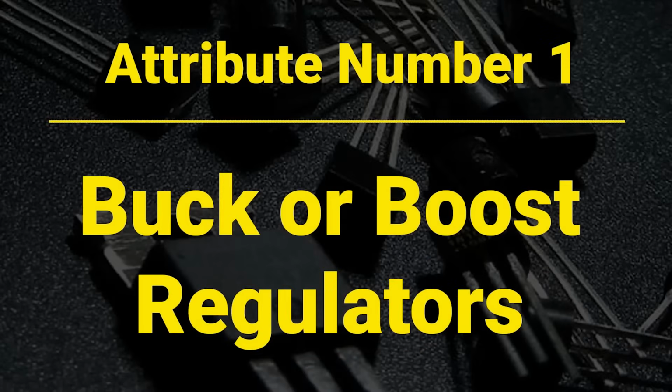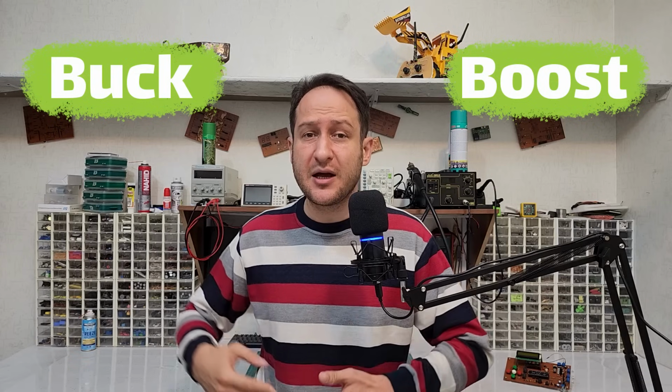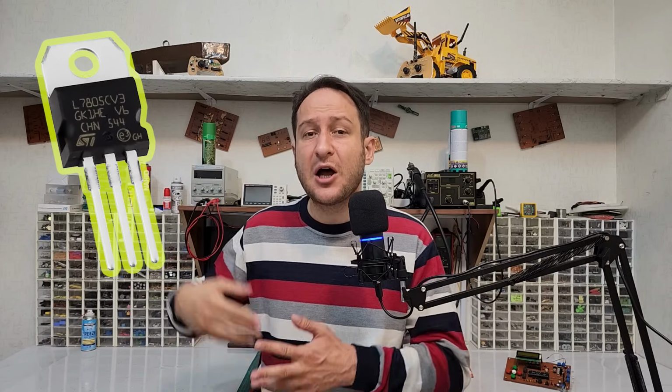Attribute number 1, buck or boost regulators. Voltage regulators fall into two major categories: buck regulators and boost regulators. Buck regulators are able to regulate a higher voltage to lower voltages. I mean, stepping down the voltage, like this L7805, which is able to convert high voltages like 9 volts or 10 volts or even 12 volts to 5 volts.